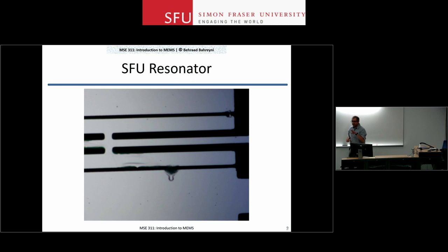The reason that I said this was a lucky observation is that usually those kinds of defects happen deep inside the device, well below the surface, so you don't see anything from the top surface. Your device was working just fine. You played with the voltage a little bit, and all of a sudden it looks okay, but it's not working anymore. The reason is that something inside that gap has shorted and rendered your device useless.